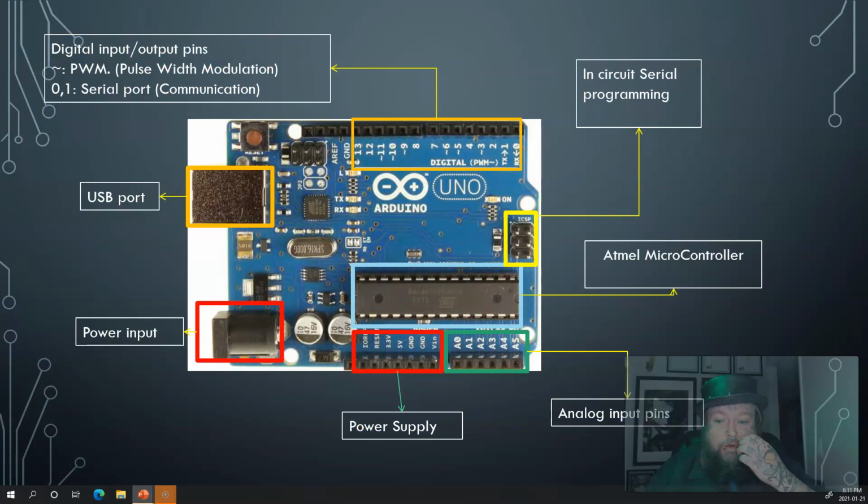Now, other things that you're worrying about, and I'm not going through all of these, is to understand, as I said again, that pin breakdown. You're used to things like your GPIO being digital, you have other connectors, and you have a whole range of power pins: the 3.3 volt versus 5, since some sensors need a different amount. You have ground, and you have things like VN, which you don't need to worry about, but it's what's called voltage in, a different way to power it.